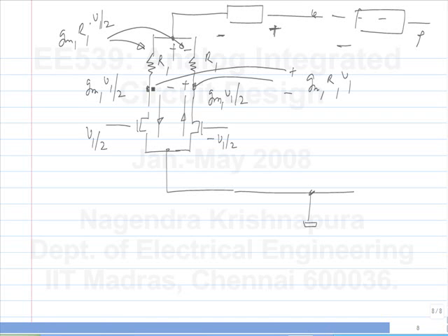Then when you look at the difference voltage, it will contain only the desired quantity, not the effect of currents through the power supply impedances. So this is a very strong motivation to use differential circuits.